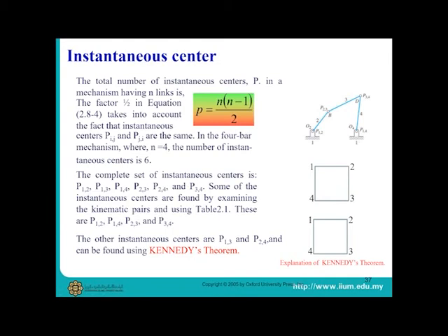Before you use Kennedy's theorem, you need to make sure that the mechanism drawing is accurate to its dimensions and position. Otherwise, you will get a wrong answer. In the exam, you need to draw accurately using a proper scale for the mechanism. For a 4-bar mechanism, you need to draw a square and write the link number at each corner of the square. Then, you need to create triangles within the square. A triangle will indicate points on the mechanism.